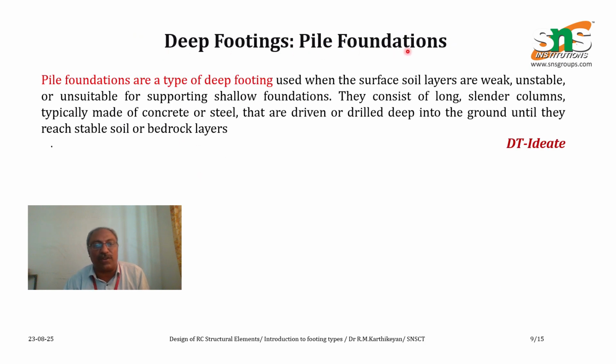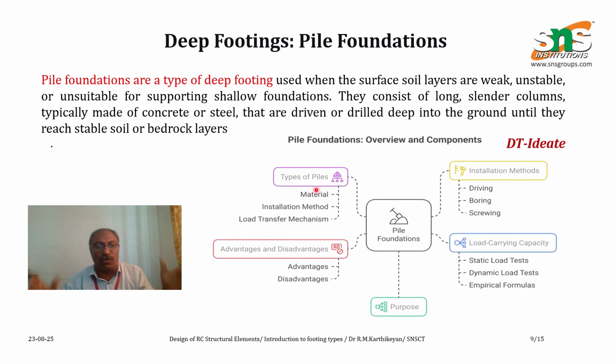Deep footing is pile foundation. All bridges are constructed on deep footing because an enormous load is transferred without any settlement. Settlement is very important. The advantage is that enormous load can be carried, and the disadvantage is that the construction cost is heavy. Pile foundations are a type of deep footing used when the surface soil layers are weak and unstable, such as clay or sand.